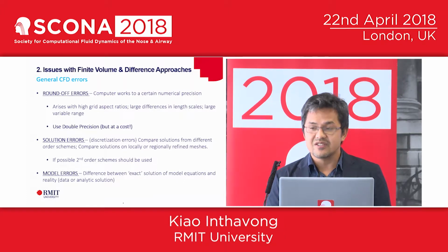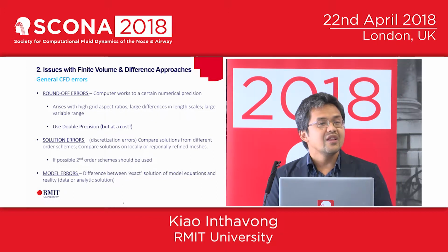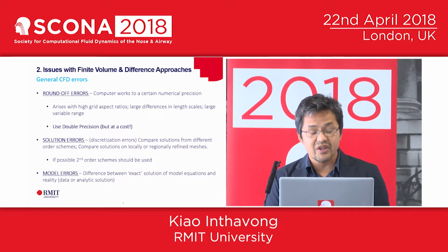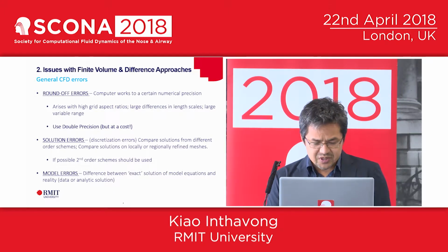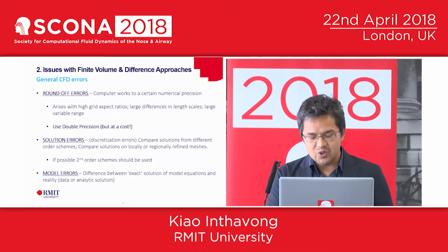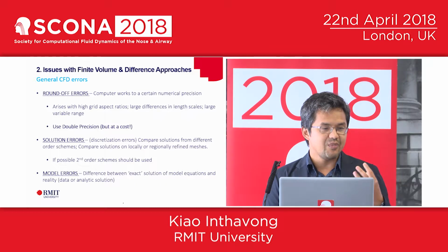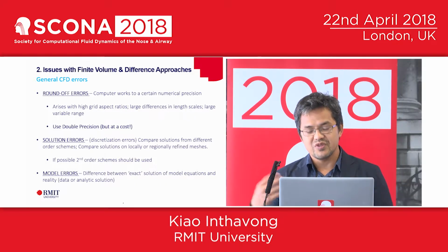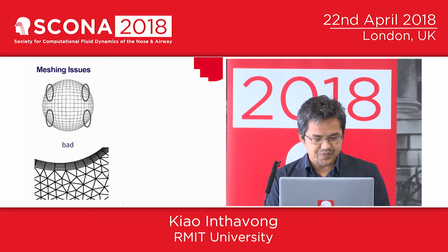Solution errors is the discretization when you're switching from the equations into discrete points. And again, here we recommend that if possible, second order schemes are used. And then the modelling errors. And as I talked about before, is which turbulence model you use and which models are you going to use to represent the physical behaviour.